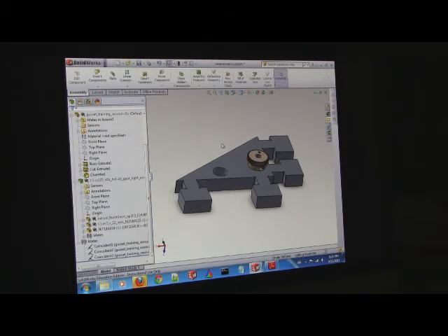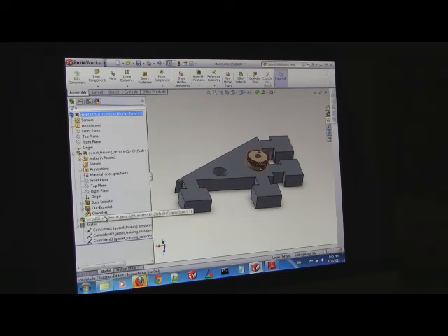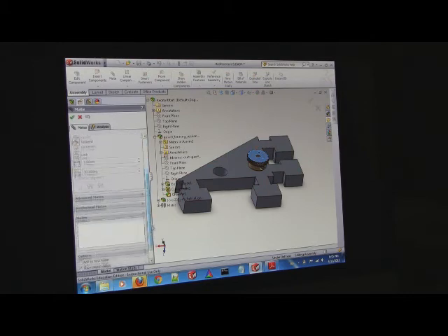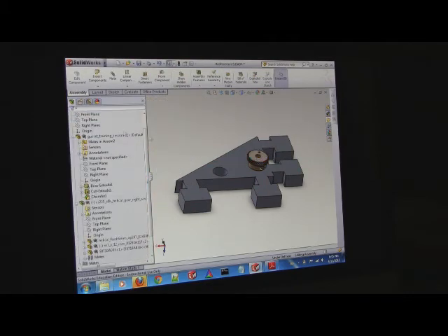Now, just a quick note, why is this dangerous and why do you have to do it in the left? It's an assembly level mate. We didn't mate with this gear, we mated with the assembly that contains this gear. If you click this gear and hit view mate, it'll show you stuff, possibly, within that subassembly, and if you start deleting that, you really get screwed fast. Never right click a subassembly and look at mates and delete. Always go to this list, make sure you have the actual assembly, and then view the mates.